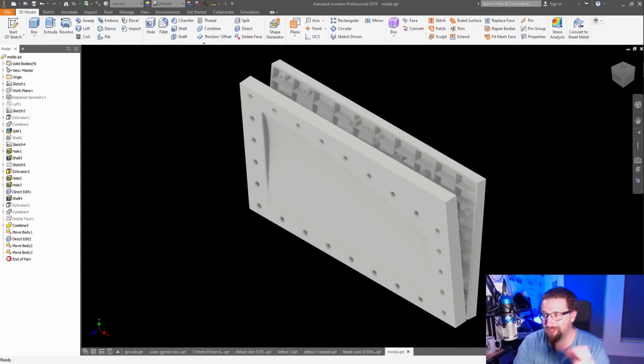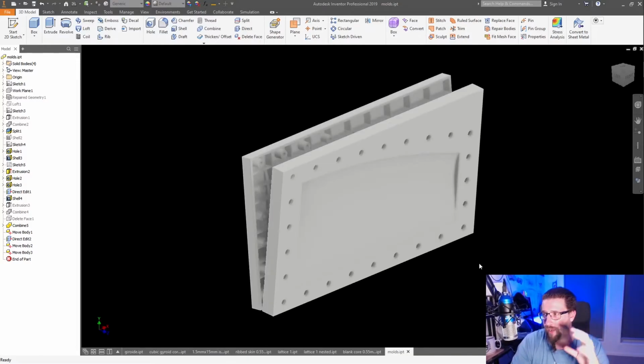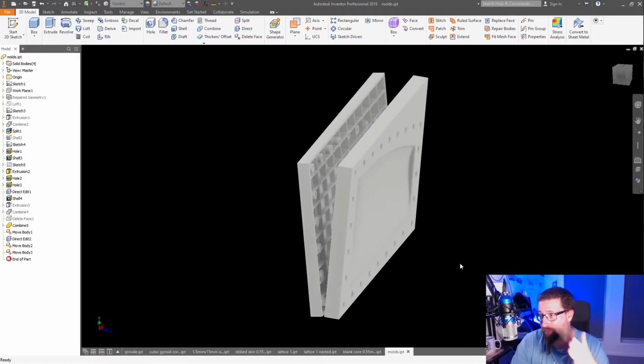We can just print molds and we can make them with fiberglass. I have some fiberglass here. I don't have any carbon fiber. I'll have to order some to test it with carbon fiber, and I think I'll have to order the correct kind of resin, because I do not think that UV curing resin will cure in a closed mold with no UV light. So I think I'm going to have to get 2-part epoxy resin so I can do this properly. But I do have fiberglass fabric and stuff that I can do this with.